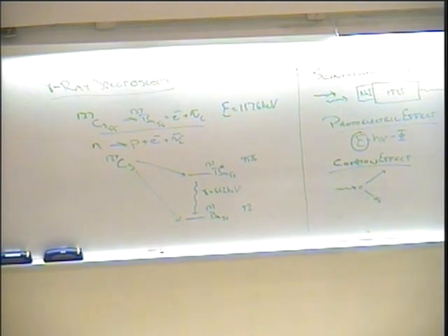Okay, yeah. So you're going to see a pulse that looks something like that. The rapid rising edge and a slowly tailing off edge from the energy being depleted out of the photomultiplier tube, okay? And this is not going to be this clean on your scope trace. This is going to have a lot of noise on it, all right? But this is the photo peak. This is the peak due to the photoelectric effect, all right?